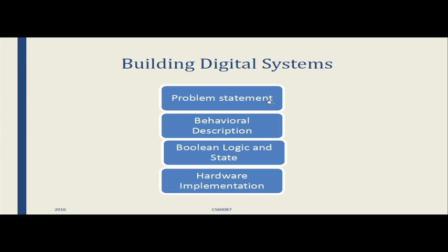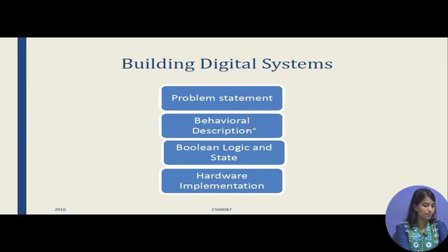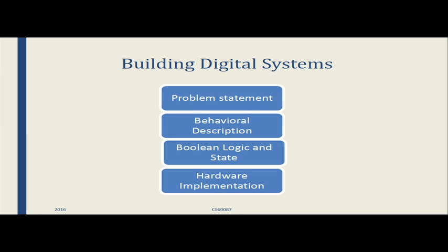So once we document the problem into a specification, we move on to describe the behavior of the system. So we go on to the behavioral description of the system. In the behavioral description, we define the operations, functions, processes, etc. that are required to convert the inputs of the specification into the outputs. That's what is done in behavioral specification. We generally design algorithms, and we put the functional operations etc. in flowcharts and RTL description. We'll come to that later, what is an RTL and all.